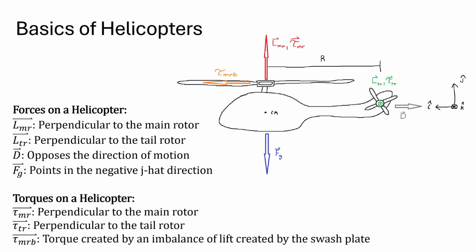However, that will also generate its own torque through the spin of the motors rotating the tail rotor, and we will deal with that through the torque from the main rotor blades that's caused by the movements of the swash plate, which we'll get into in a lot more detail now, but for now we don't really need to explain that. And so that will stop the torque from the tail rotor to cause us to rotate. So we can stop both of those.